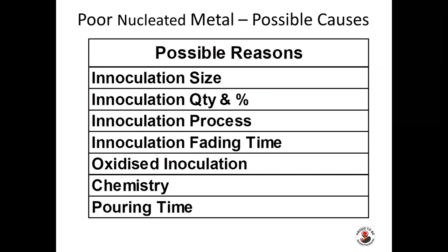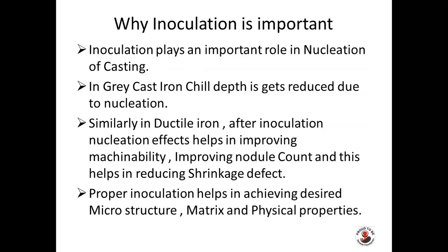Inoculation size. You have to define that size based on your ladle size and metal treatment size. Inoculation quantity and percentage, inoculation process, inoculation fading time, oxidized inoculation, chemistry, pouring time. Why is inoculation important? Inoculation plays an important role in nucleation of casting.